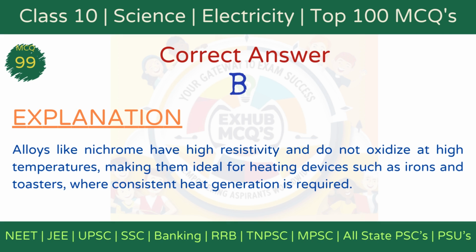Explanation. Nichrome is preferred in heating devices due to its high resistivity, which allows it to generate heat efficiently. It also resists oxidation at high temperatures, making it durable and effective for applications like electric heaters and irons.